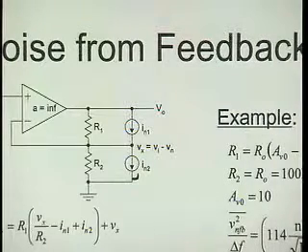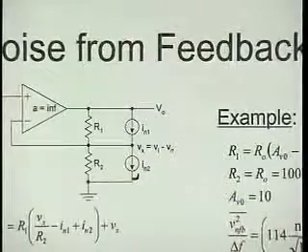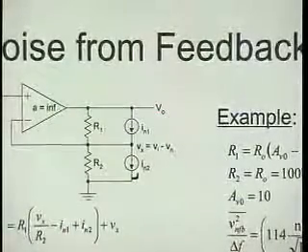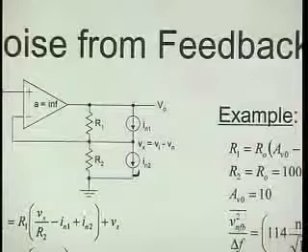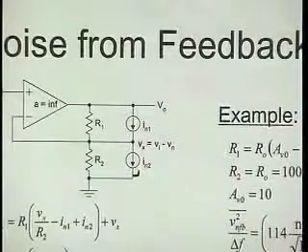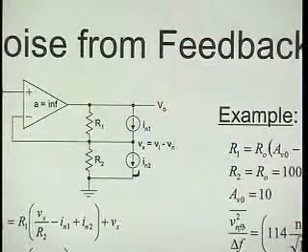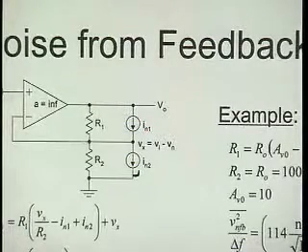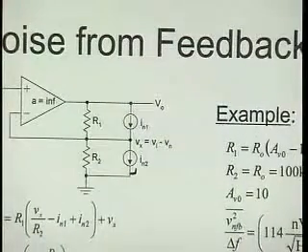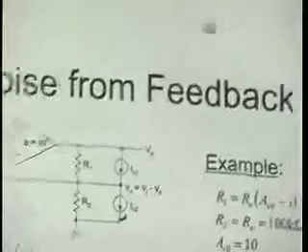Yeah, we can make the noise small, but we need to make these resistors tiny small. And then you need to drive them, right? Now you need a bigger amplifier to drive this garbage. Well, fortunately, it's Boltzmann that's stuck in there. The guy in the next cubicle or in your competitor's company has exactly the same problem, except that he probably doesn't understand it, and so you're one better. All right, so noise from the feedback network cannot be ignored.